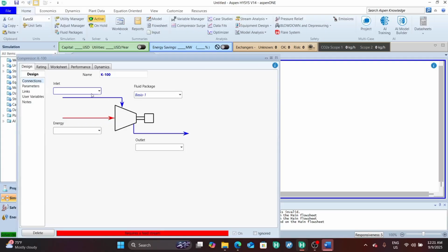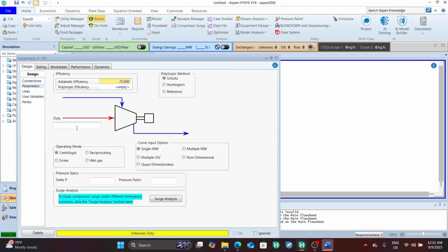So plug in our air stream, label this as Ecomp1. Just fix that up. Ecomp1 outlets compressed air 1. We specify our pressure, change in pressure. It's an increment, remember. Let's just say this is about 2.5 bar. Good.